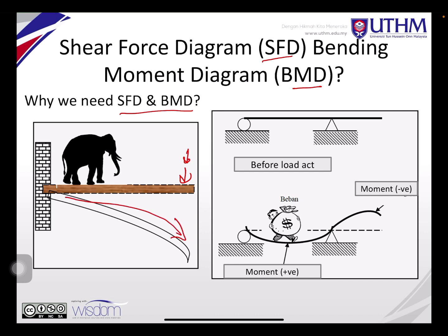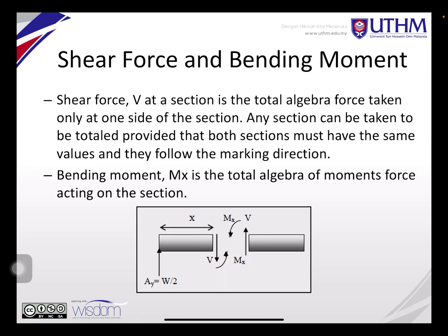By logic, when you apply the load here, this beam will bend downward. Also, you can see you have a roller support here and a pin support here. When you have a load applied like this, here is going to bend down, and here is going upward, moment positive, because when you push something here it will affect it going upward. So, shear force and bending moment.